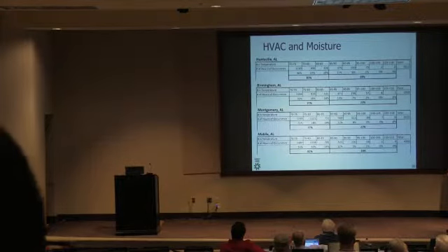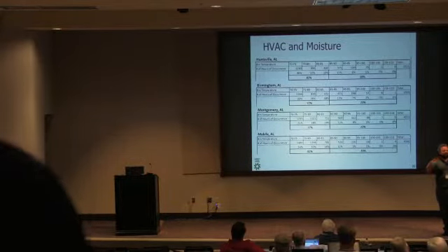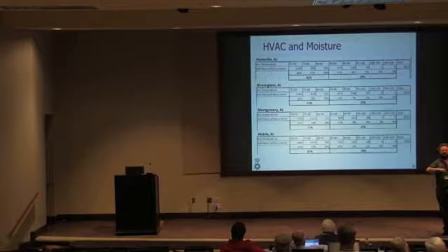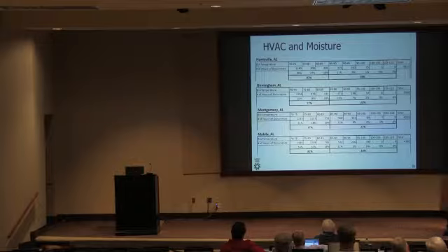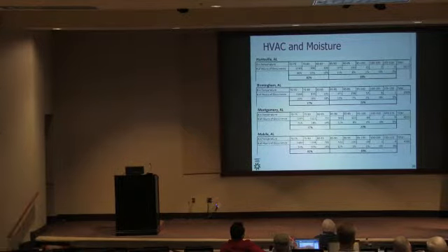Remember what I said at the beginning? You got to get that interior coil up to steady state, solid state operation before it starts wringing moisture out of the air. About 10 to 15 minutes of runtime before it starts to dehumidify. So in order to dehumidify effectively, what you want is lots of air slowly drawn over a coil for a long period of time. So the best comfort is actually provided today by variable speed equipment, where we can slow down the speed at which air is being drawn over that coil, and we take longer to reach set point inside the house, and we're effectively dehumidifying, and we're getting lots of runtime on the equipment.